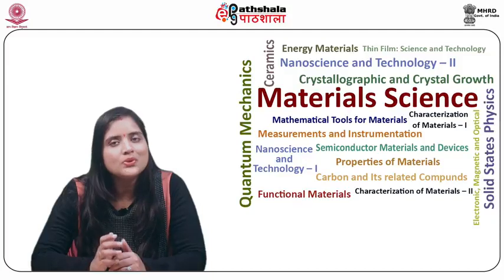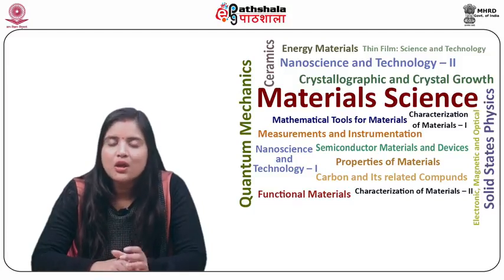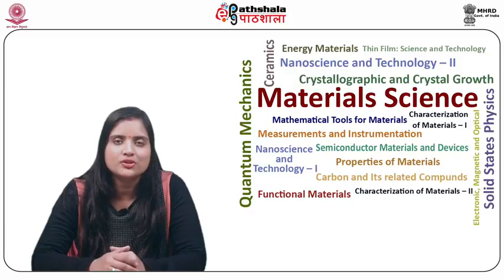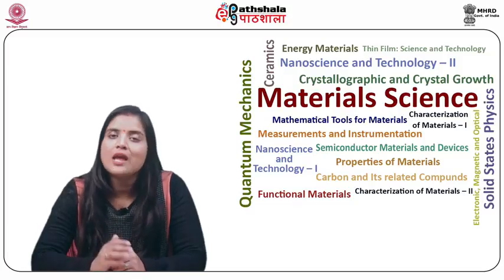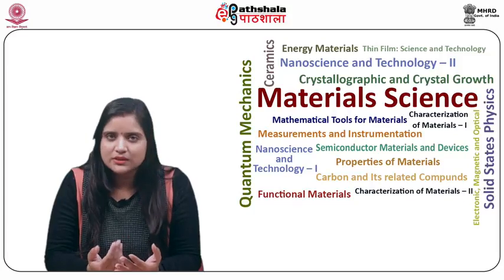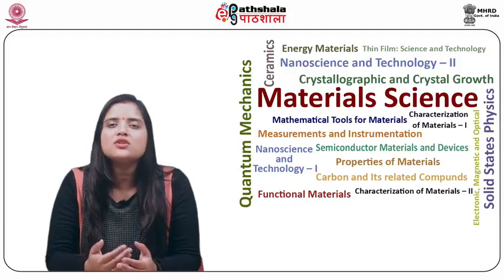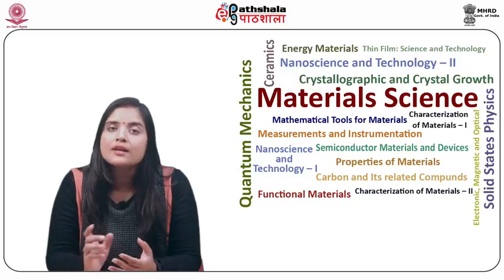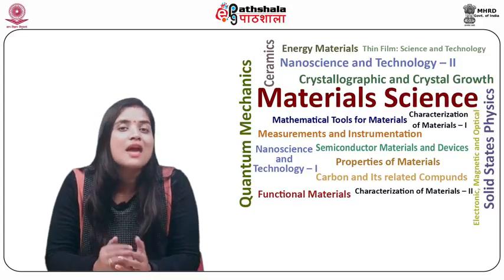This technique can be used to grow materials which have high vapor pressures at melting points. Moreover, hydrothermal processing can also be used for producing large and high purity crystals having well controlled compositions. The limitation of the method includes the inability to observe the crystal during its growth. Hydrothermal synthesis is affected by the temperature and pressure below a critical point for the particular solvent. Some oxides are more soluble in the hydrothermal salt solution in comparison to pure water. These hydrothermal salts are termed as mineralizers.